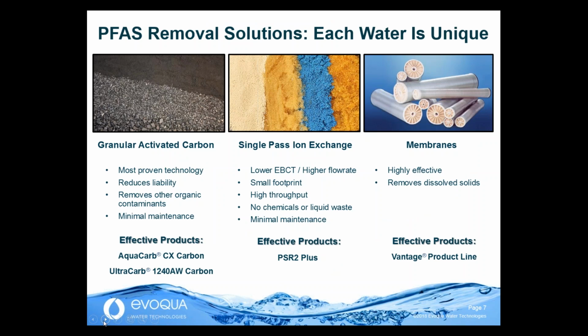So this slide shows the most commonly used treatment methods for PFAS removal. So starting on the right-hand side, we have membranes. And for membranes, they're highly effective at removing a wide range of PFAS, and they'll also remove any dissolved solids in the water as well. But it is important to keep in mind that they do have a higher capital cost, and they are going to produce a liquid waste stream that would then need to be managed.